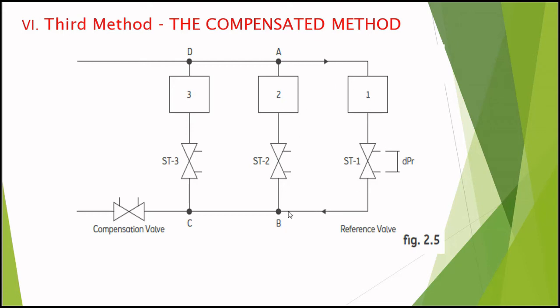So the reference valve is the one which we already set at the beginning of the commissioning, and the compensating valve, or compensation valve, is the one which we throttle to compensate the changes in the differential pressure and the flow in the other circuits. So these two definitions are very important to do this type of commissioning.